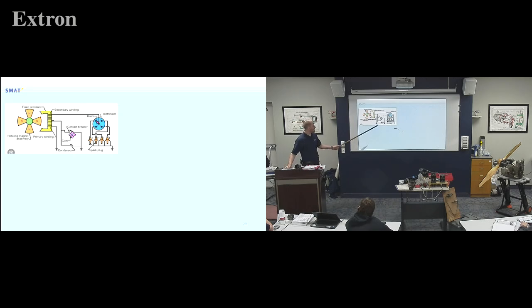Alright, so what happens then is our distributor, which is geared down slower, is going to get that voltage off of the coil that's inside our magneto. That coil off the secondary comes off this little tab, which basically runs on this carbon piece on the wheel.